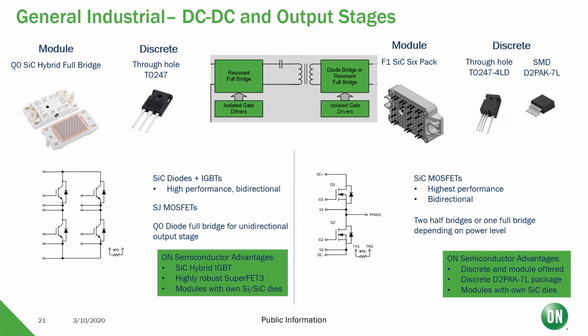We have a similar solution on the DC-DC and output stages. Again, using IGBTs and SiC diodes together, we have those solutions for low costs. But on the right side, we have standalone SiC MOSFETs, which again can be used for the best performance and the higher power levels.